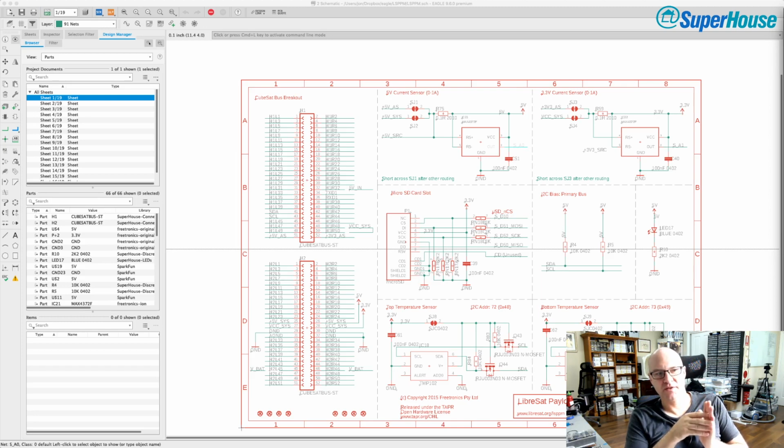If you could modify the circuit board, like you could cut a track with a Dremel and you could connect to the second output of the relay, like the normally closed output, then you could wire it up with an external switch in the same way as you would do a two-way switch, like a passage light system. And that would work. Then the Sonoff could fire and turn the light on or off, and then you could flick the switch and turn the light on or off.